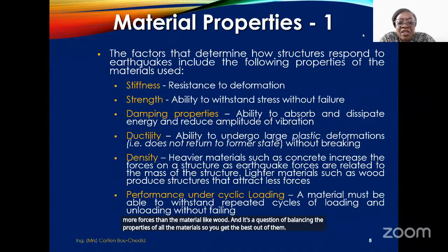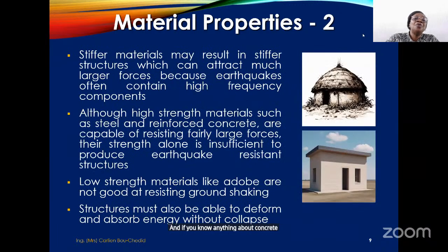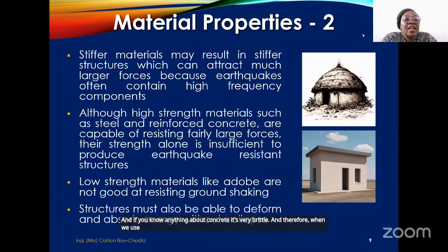And of course, the most important being the material should be able to withstand repeated cycles of loading and unloading without failing. And if you know anything about concrete, it's very brittle. And therefore, when we use concrete in buildings, we have to treat it well so that the structure is able to perform in a ductile manner.